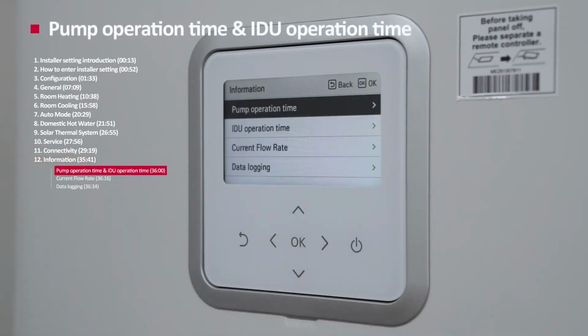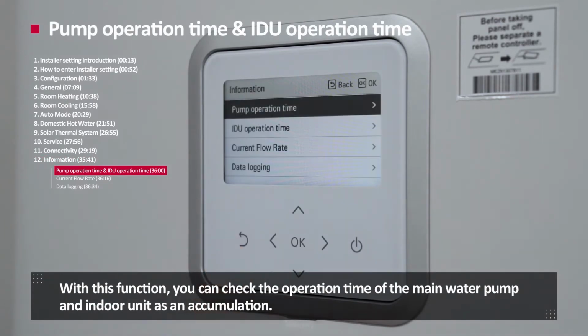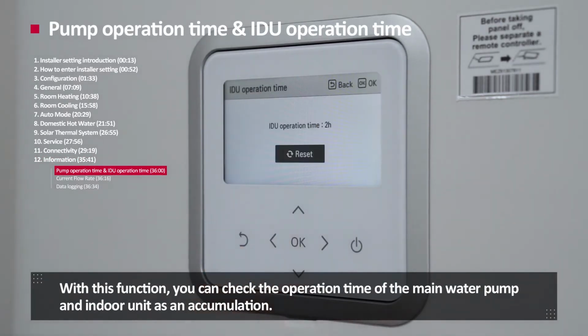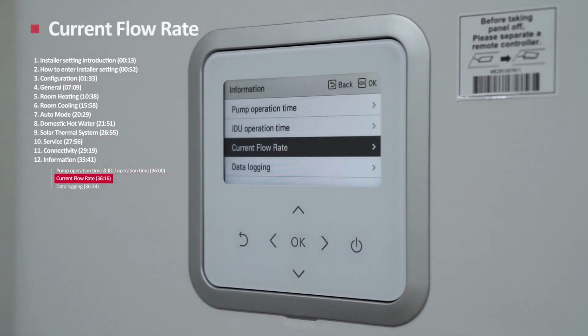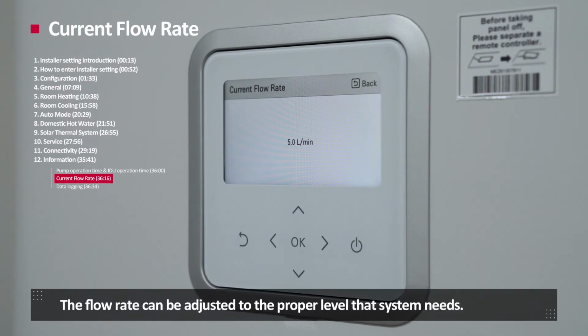Pump operation time and indoor unit operation time. With this function, you can check the operation time of the main water pump and indoor unit as an accumulation. It helps to estimate the mechanical life of them. Current flow rate. Current flow rate displays the current real-time flow read by the built-in flow sensor. You can instantly check if a pipe or strainer is clogged or not. The flow rate can be adjusted to the proper level the system needs.